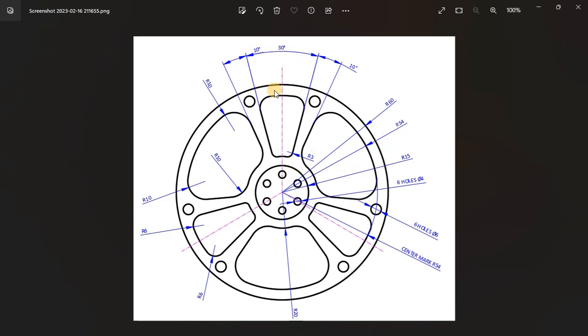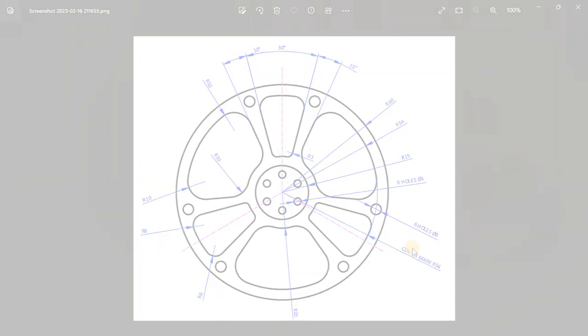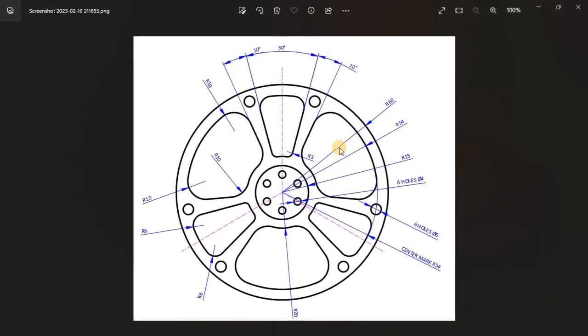Okay, so let's go over to AutoCAD and start with the big circle. The outer circle has a diameter of 60 times 2, so we just take the radius, that's 60. Then the next inner circle has a radius of 54, and then the one that follows will have a circular part here. This one has a radius of 20.